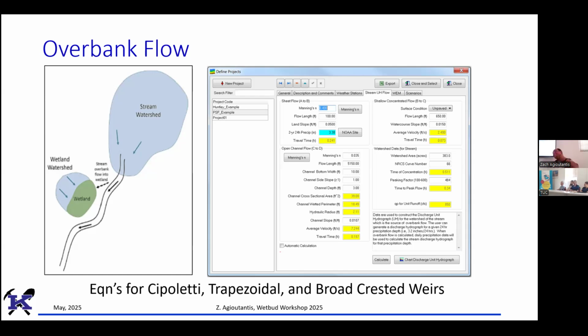Any other questions? Okay. Now, going back to Maria, you asked what the weir is. We have a weir right here. That weir is for outflow of the wetland. We also have channels that may be used to feed the wetland with water. Those channels also may have a weir. So the program allows for input weirs, and there are three different methods, three weirs, that can be used to control input into the wetland. I'll show you that in a few minutes.